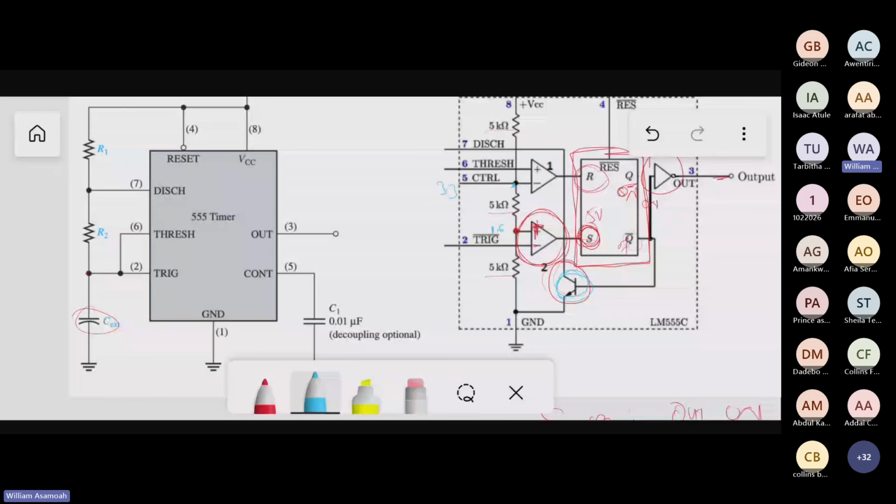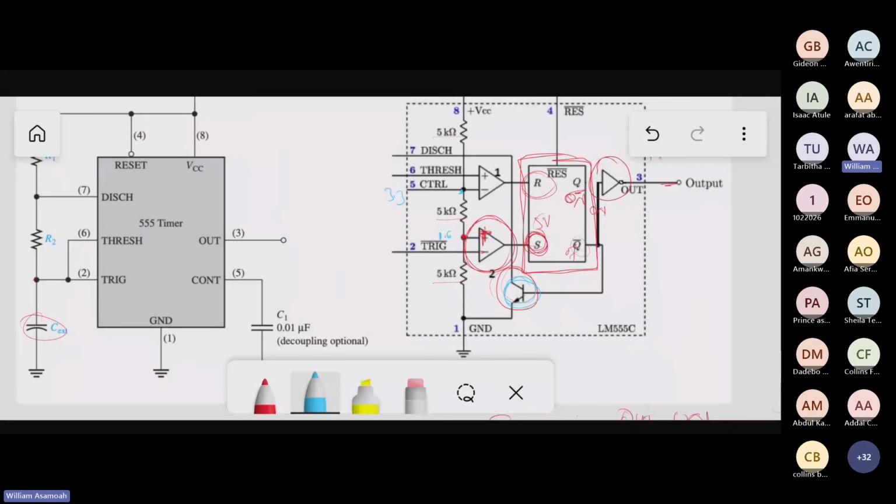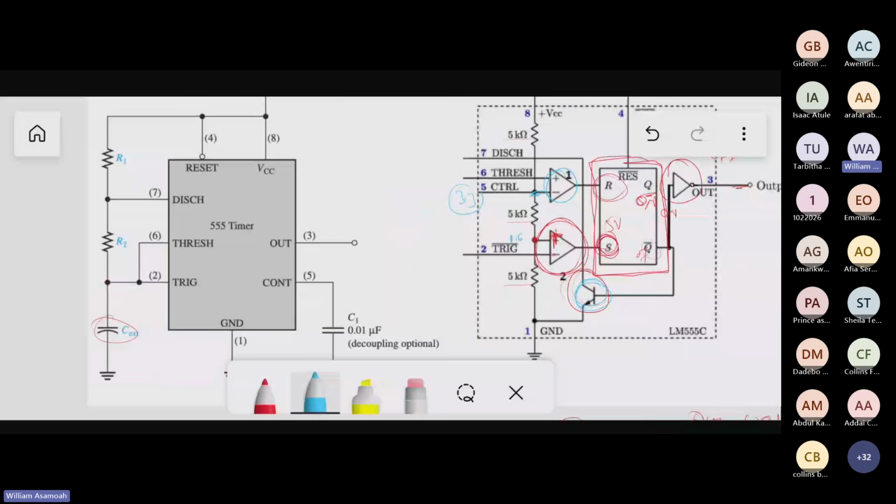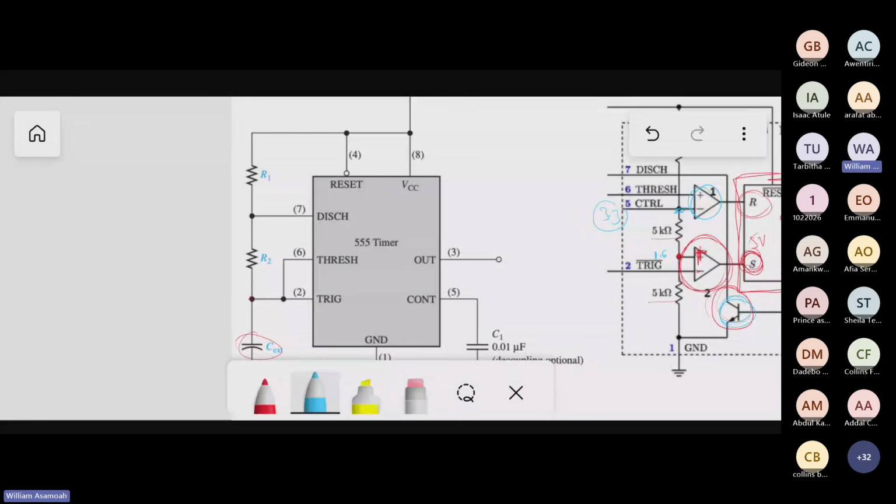It's still rising. But this comparator is connected to 3.3 on the negative side, and the one it compares to is the threshold, which is still at the output of the capacitor. So we are monitoring the capacitor. Is it charging?